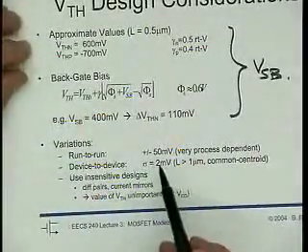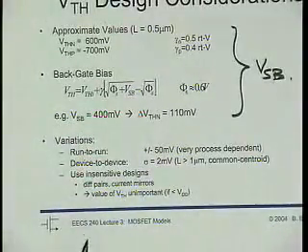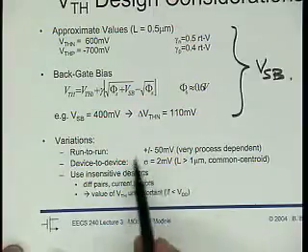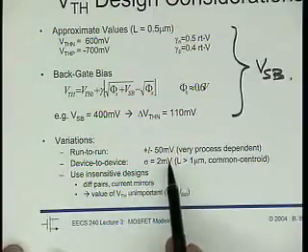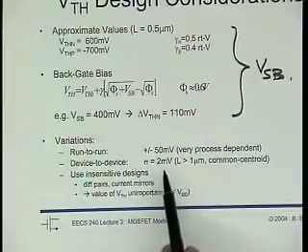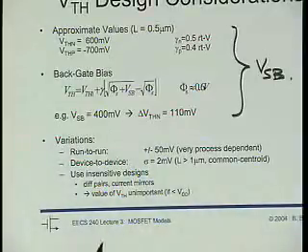Right? Sometimes we need this. Run-to-run variations of threshold voltage. Right? Threshold voltage target value for 1 micron device, 600 millivolts. Well, as you get runs, they will be distributed over 550 to 650 millivolts. For another process, of course, the distribution may be broader or narrower. Device-to-device matching, if the devices are close together, is a lot better. And again, it depends on channel length. So for reasonably long channel lengths, a micron or so, the variation is maybe 1-2 millivolts or so.